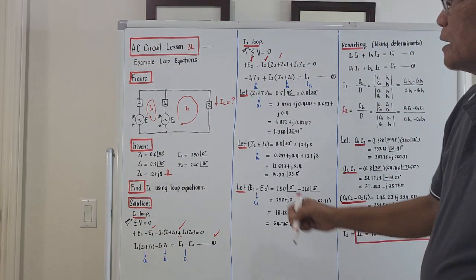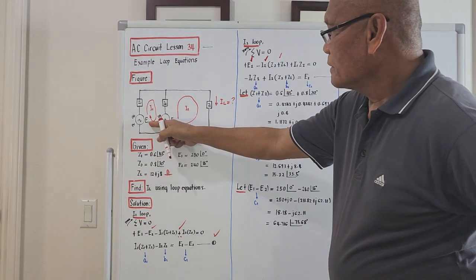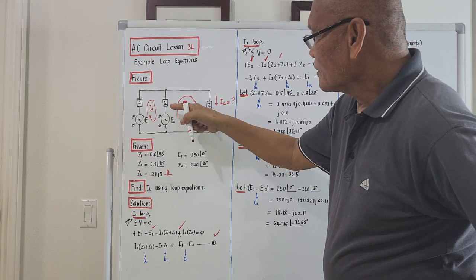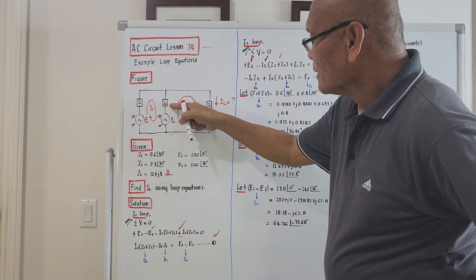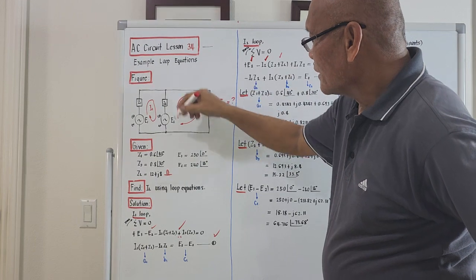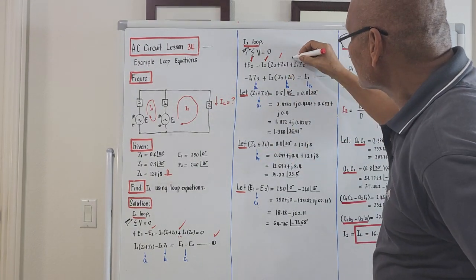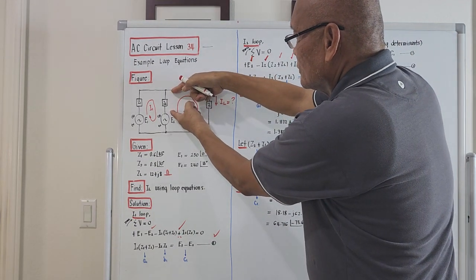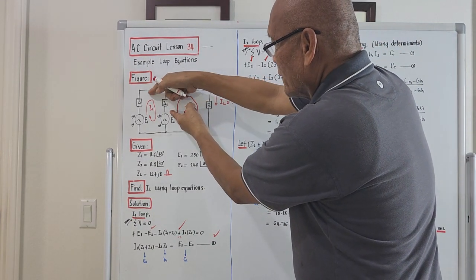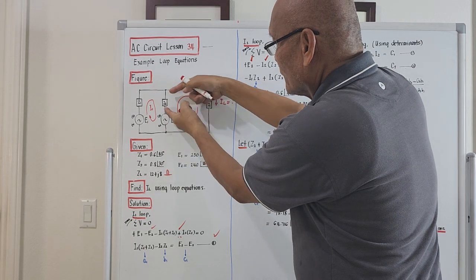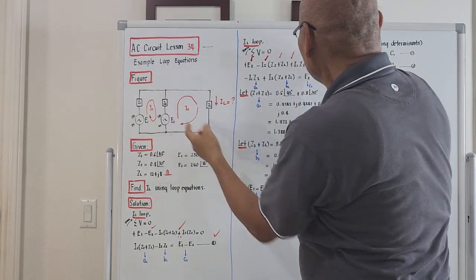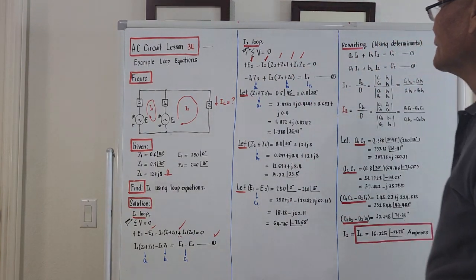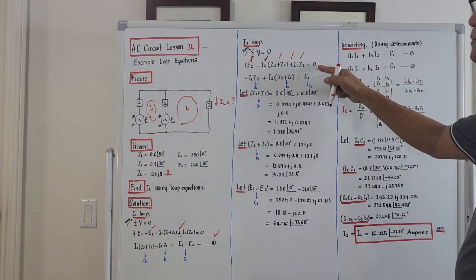Okay. There is an effect of I1 on the I2 loop, okay? Because it passes through Z2, right? And it contradicts the negative direction, so this should now be plus. So the voltage drop on Z2 due to I1, considering the I2 loop, will be the product I1 times Z2. This is I1 times Z2, but it should be plus, right? And this should be equal to 0.